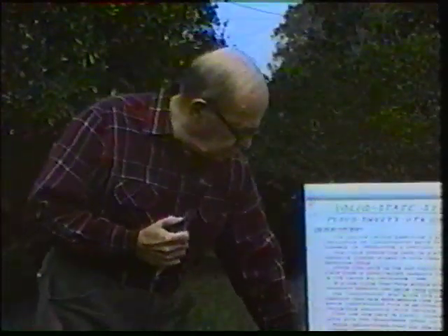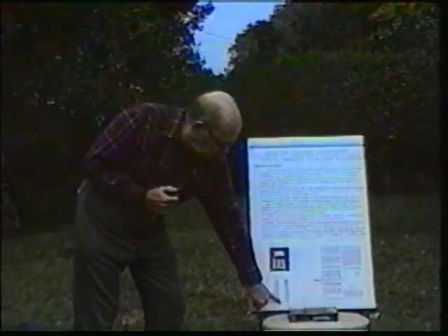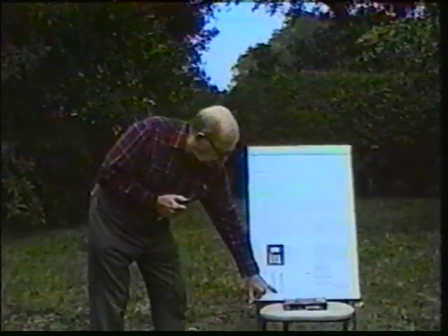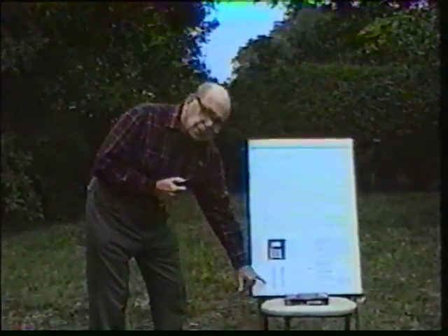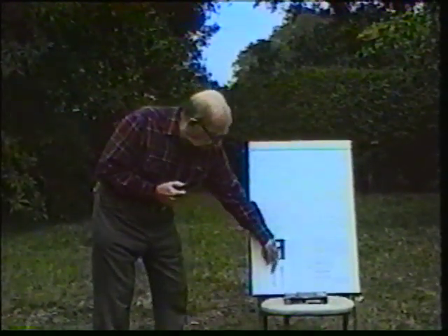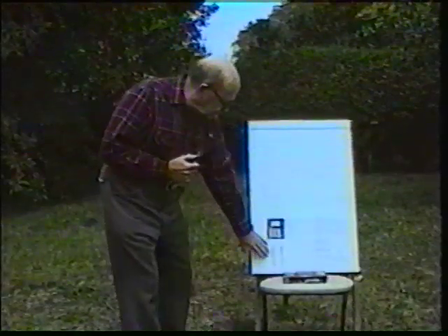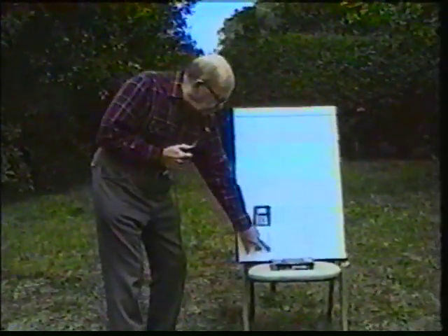So we're talking about something that resembles a transformer core with a coil wound on it. And again a bifilar, very much so. This would be a general picture, and you can always tell a bifilar because the ends of the coil always come out of the same end. You see, if you're starting one end and then coming back over itself, the two ends are going to come out of the same end. So that's very typical of a bifilar construction.